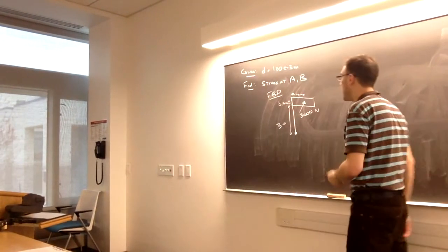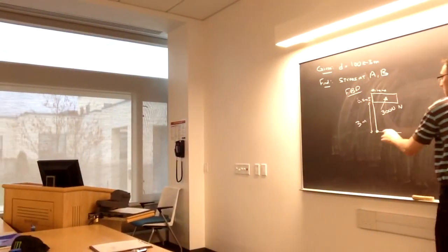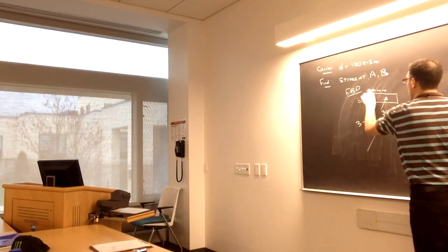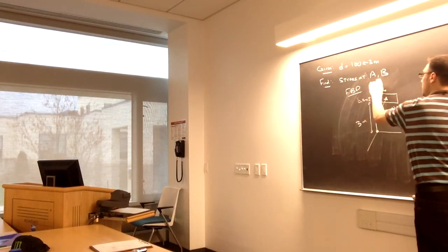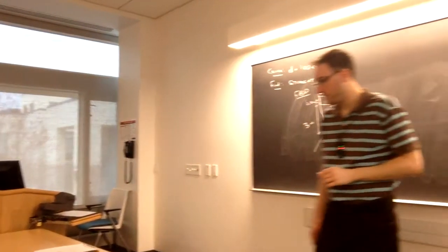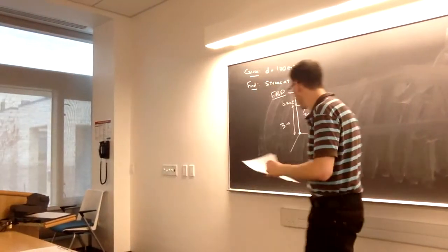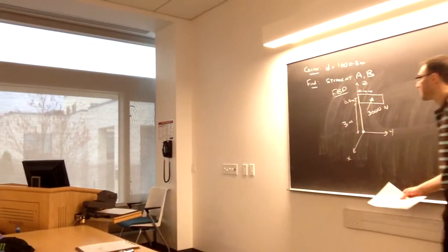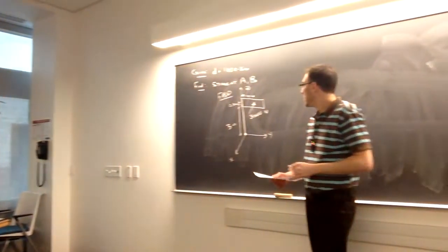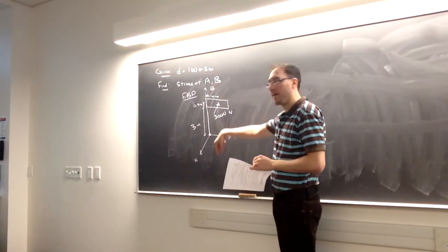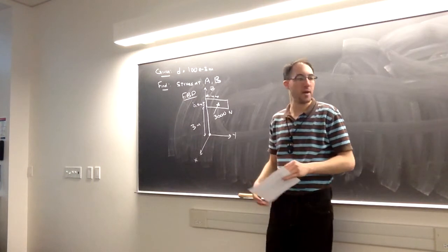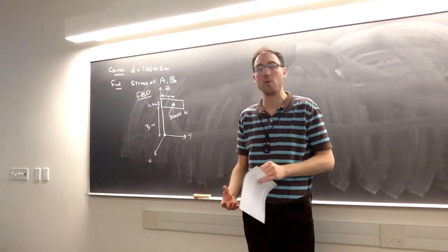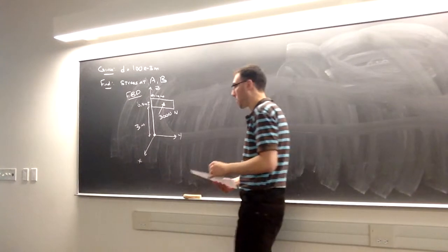I'm going to locate my coordinate system at my cut surface, like I have previously. So where I'm cutting, I have to go out from that cut surface, so I'm going to start with my internal normal force and my internal torsion here.